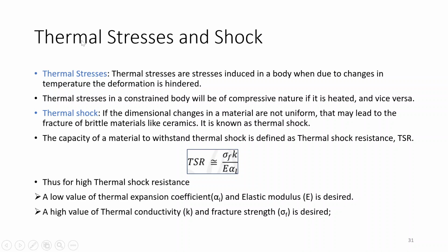Next property is thermal stresses and shock. Thermal stresses are stresses which are induced in a body when, due to changes in the temperature, the deformation is hindered. The thermal stresses in a constrained body will be of compressive nature if it is heated, and it will be of tensile nature if it is cooled.